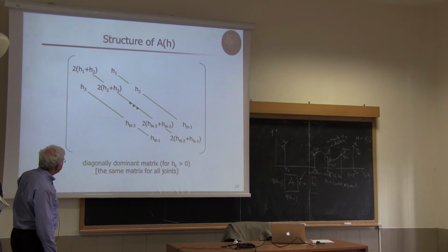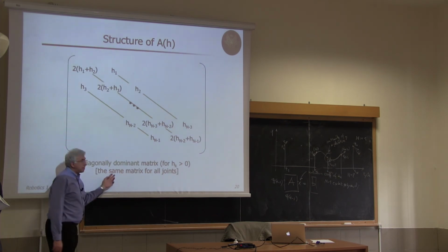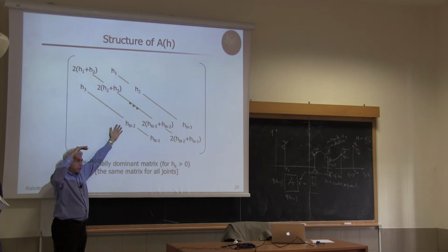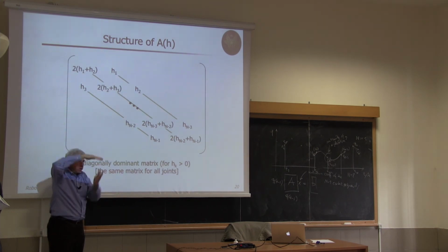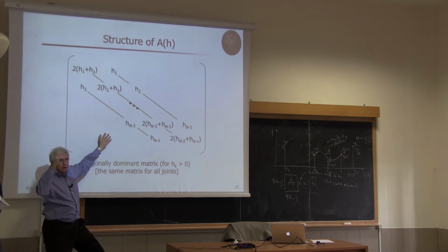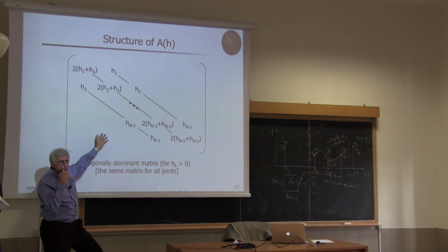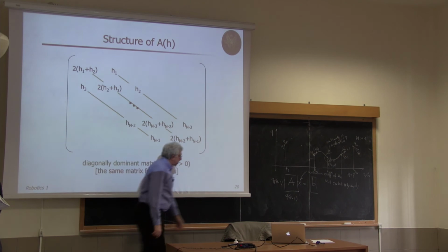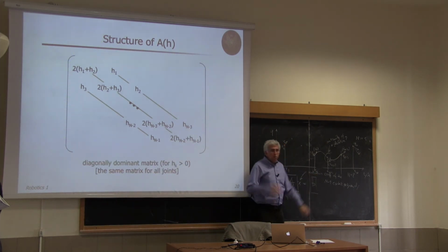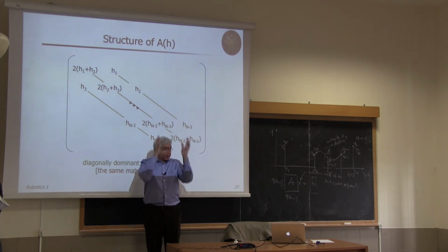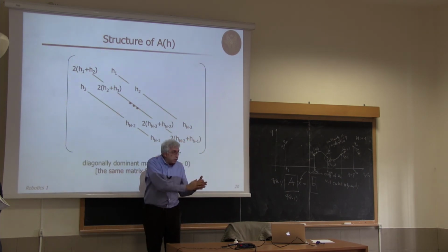Okay, and the other thing is that since there are no q's or v's here, if I have to invert this matrix for the generic joint J in an interpolation of all the joints, well, the same matrix is the one for any joint. So I have to invert this matrix only once. Okay, because only the data on the right-hand side, those that go into the vector B, will depend on the specific joint. And here there are only the intervals, and the intervals are the same for all joints because we want to make a coordinated motion.